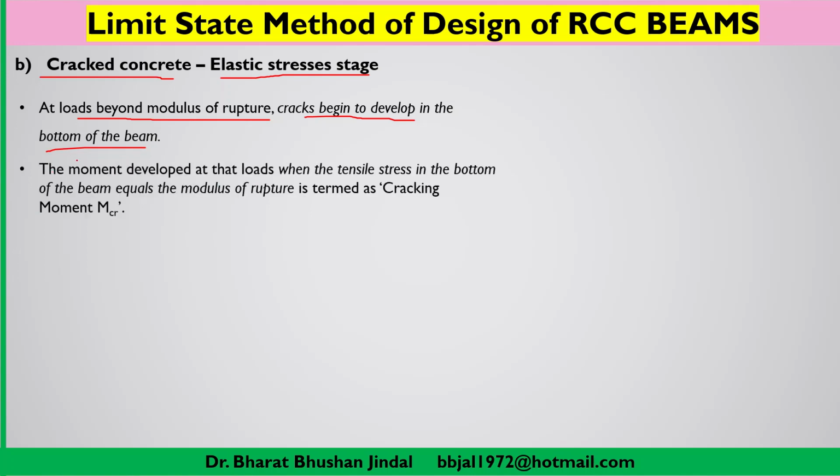and the moment developed at these loads. When some load is applied, it will create some moments. So when your load is beyond this limit, the modulus of rupture, then the moment which gets developed at that load, when the tensile stresses in the bottom of the beam equal the modulus of rupture, is termed as the cracking moment, M_cr.